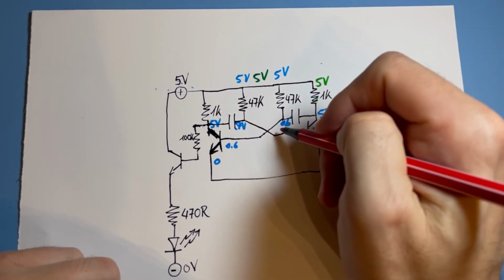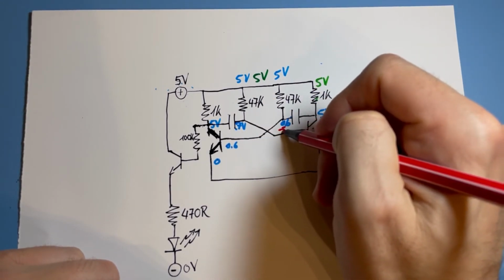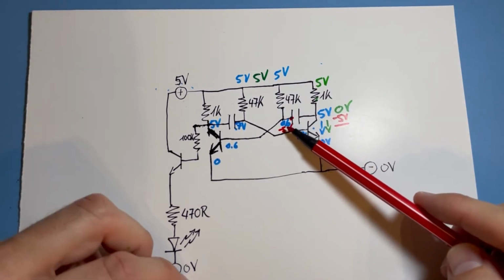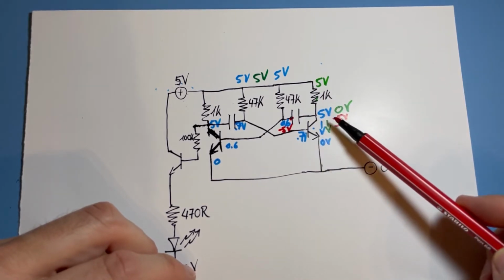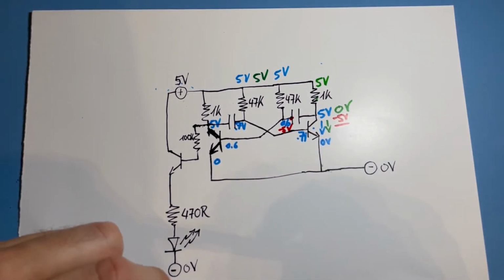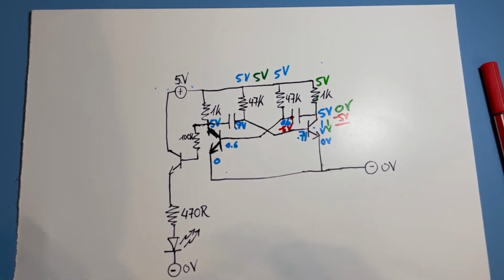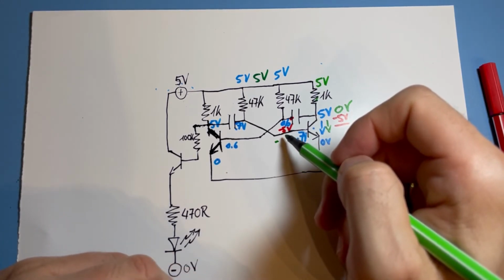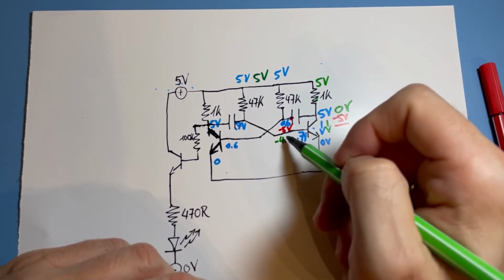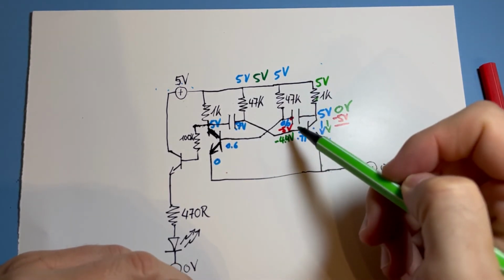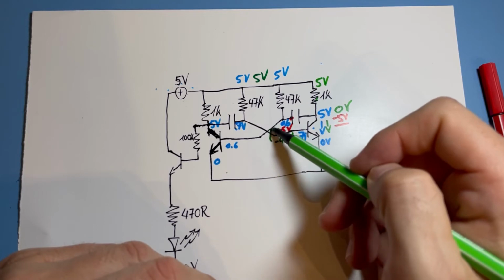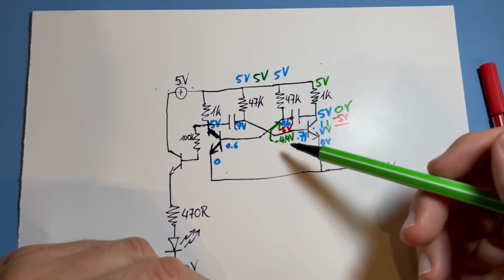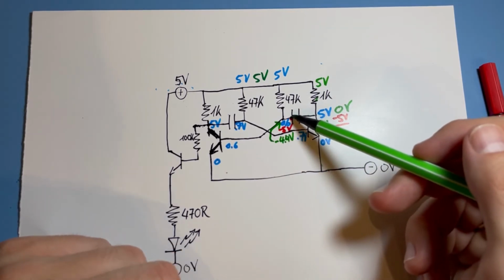You have also a minus 5 volt here at the other side of the capacitor. And if you had before 0.6, as we said, then this sudden drop happens of minus 5 volt. You have 0.6 minus 5 volt, and you won't believe me, but now you have here 0.6 minus 5, which is minus 4.4 volts. Suddenly. And I have to watch out because this is all referring to the left side of this capacitor. There you have minus 4.4 volts on the left side of this capacitor.